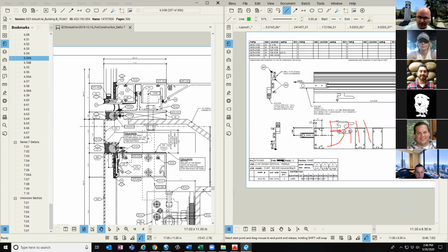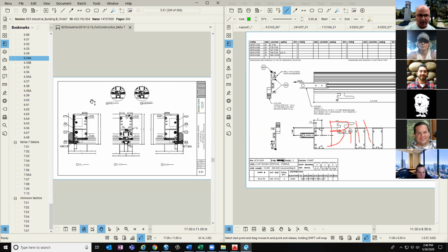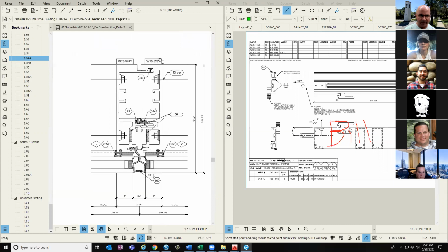So again, I'm going to verify my part numbers by going back to my elevation. You see that I'm navigating back to these shop drawing details multiple times as I'm doing this process. This is standard for us that we revisit these details many times. So as I'm going through here, it's my 5263, verifying that, and it's a painted finish. We've looked at the pre-takeoff meeting notes. I know that there's not multiple finishes on this project, so I don't have to worry about that part of it. If it says paint, then it's just a painted part.